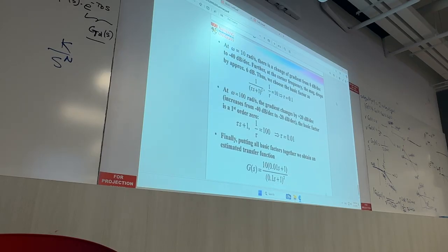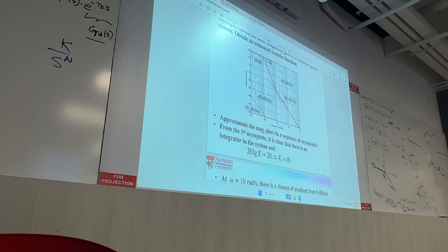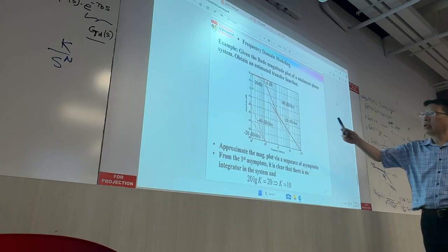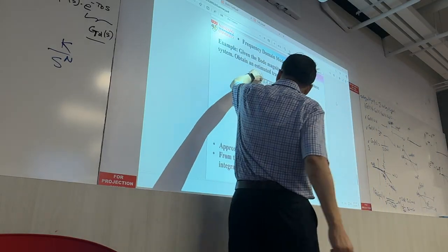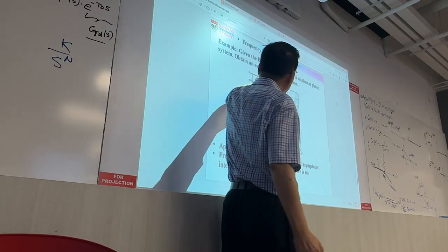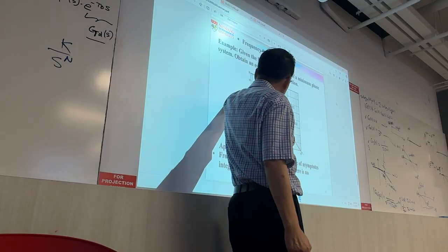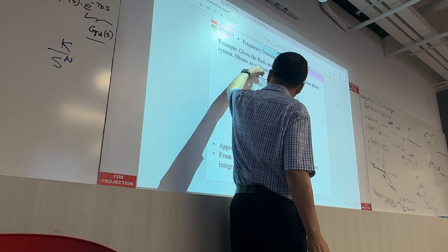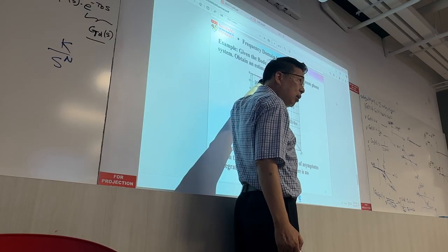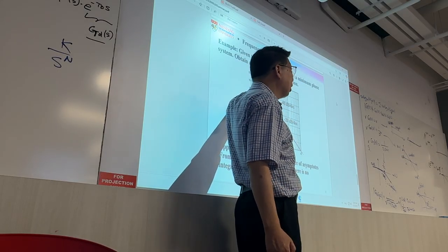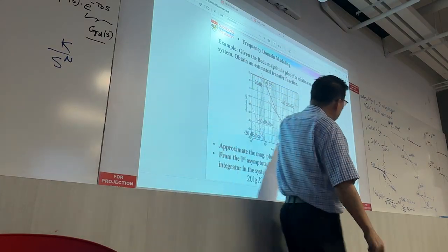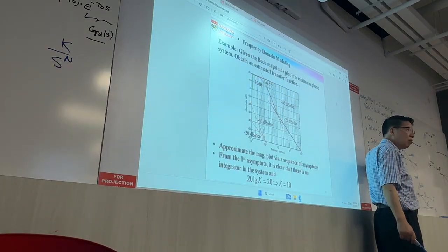And then at the next corner frequency, at this corner frequency, this is 10, at 10. This is a corner frequency at 10 or 9, it doesn't matter where you read it. Suppose you read it as 10, and here the slope changes from 0 to minus 40, which means what? Here there is a second order system, because each single one gives you a bend of minus 20.